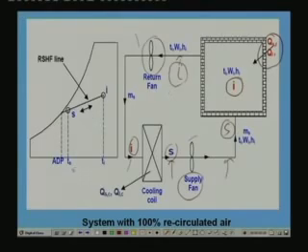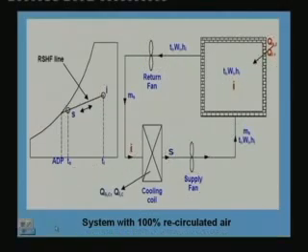So, you have the dry bulb temperature here on the psychrometric chart. As you know, on the y axis we have the humidity ratio, and this, as you know, is the 100% relative humidity or saturation curve. Okay, and point I is the state of the conditioned air inside the building, and point S is the state of the air at the exit of the cooling coil or at the inlet to the conditioned space.